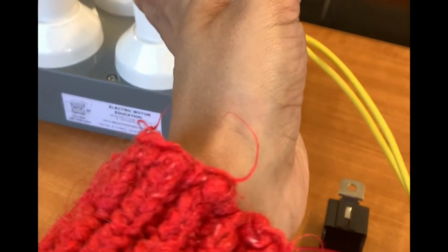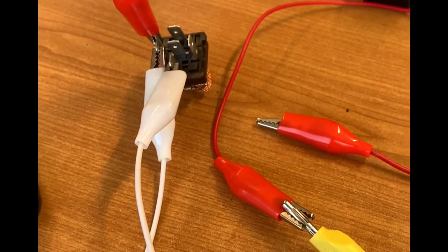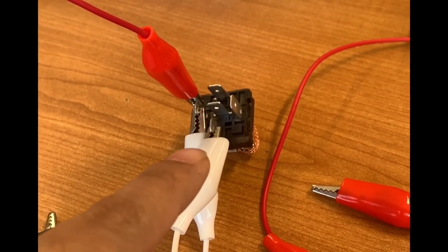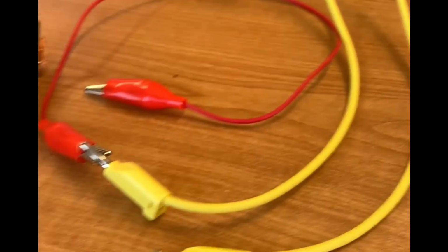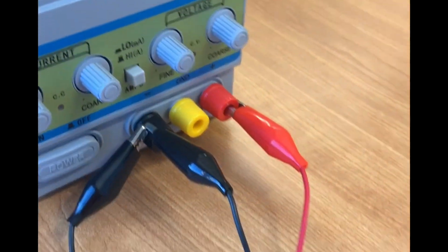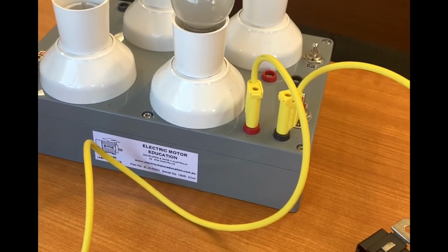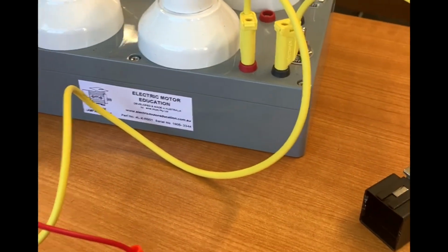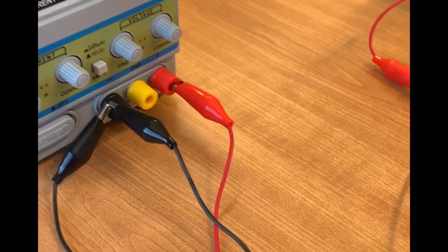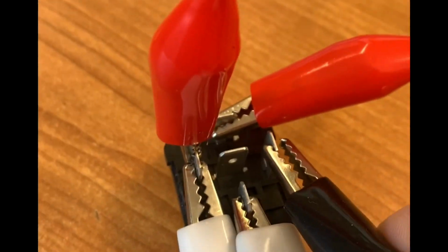Now from the switch to the rest of the circuit, whatever the circuit is. Now we want to control our circuit by this switch. So it should be in series, right? So the power, DC power, is coming in to our switch and going out to this light bulb. And from the light bulb, from the negative, it's going back to our power supply. So I'm going to put this positive, as you see, to the positive side of the light bulb. Well, this light bulb doesn't have any polarity. It doesn't matter which you put where, but because this is red, I'm just trying to respect the polarity. And then from the other side of the light bulb, we're going back to the negative. The negative of the relay is connected to the ground, so it should be connected to the ground.